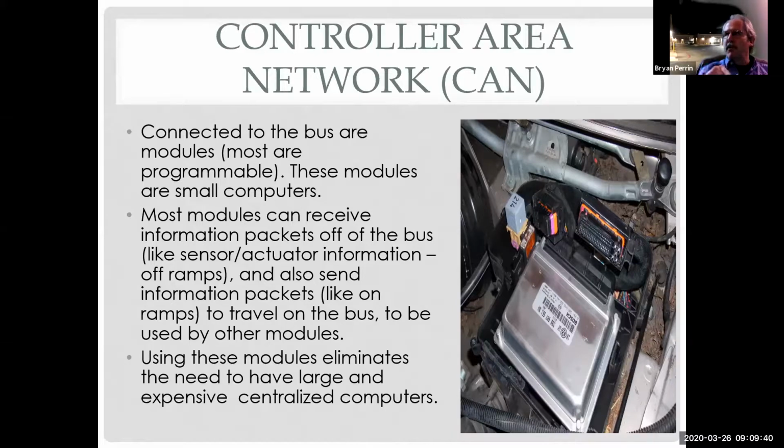So one thing the book did pretty good, and the book PowerPoint I'll talk about a little bit, is pass-through programming or programming modules. A lot of modules come what we call dumb. All the hardware is there, but not the software, or just basic software, allowing it to get on the network. And then we actually have to hook a tool up, contact the vehicle manufacturer's website, and download the data for that to work on that particular vehicle as that vehicle is built.